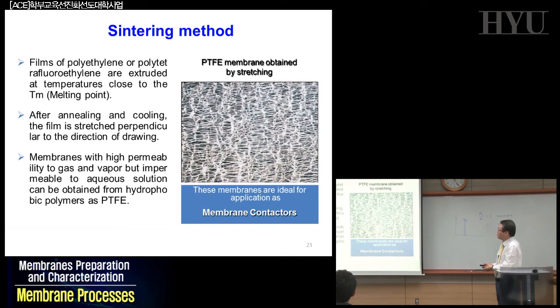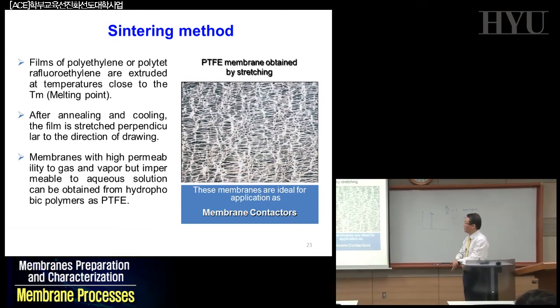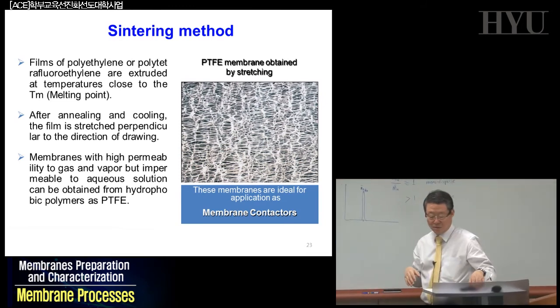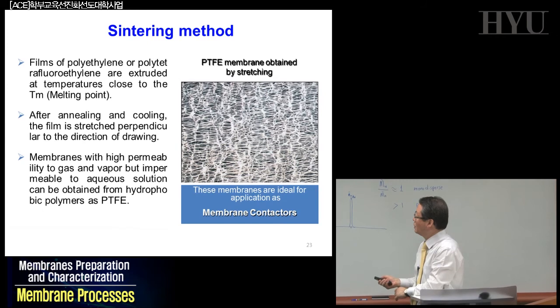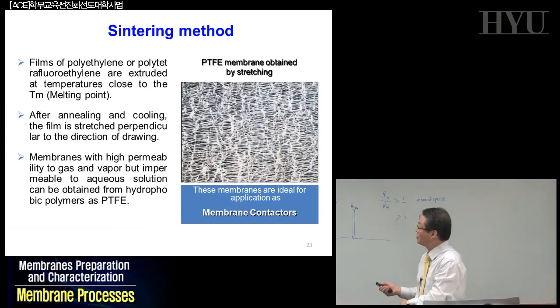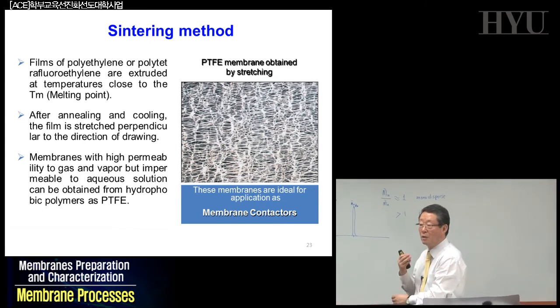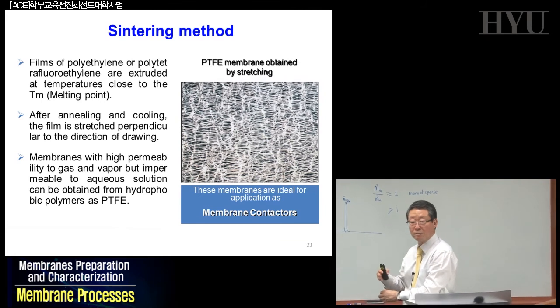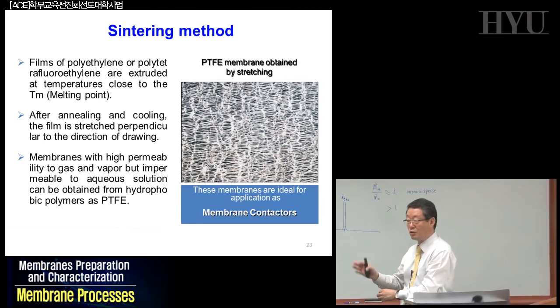In some separation applications, they do not want a hydrophobic surface, so they sometimes make a hydrophilic surface out of this PTFE membrane by plasma polymerizing or surface treating for some purpose. I think you can take a look at some of the other applications.